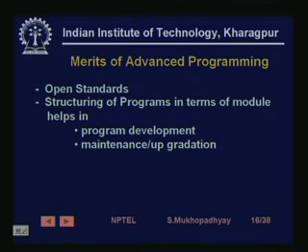Then structuring of programs in terms of modules helps in program development and program maintenance, very important. Program upgradation: if you want to add a new functionality, you will find that it's very simple. Just change the state diagram, and if in the new state diagram you have 3 extra states, you simply add those corresponding rungs. If you have some extra transitions, you add those rungs, and if you have to redirect some transitions to new states, then you code that logic in that state logic. So you absolutely know which are the places where you have to make changes. These are the very standard benefits of structured programming.